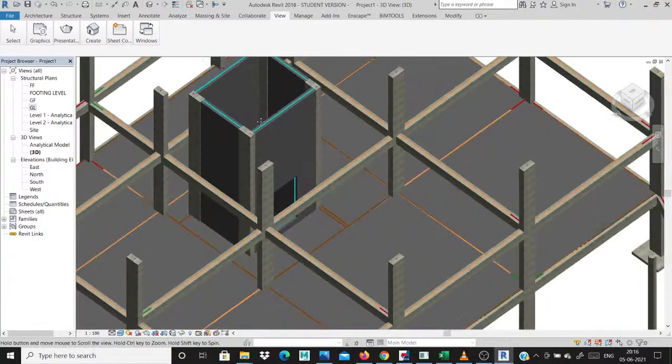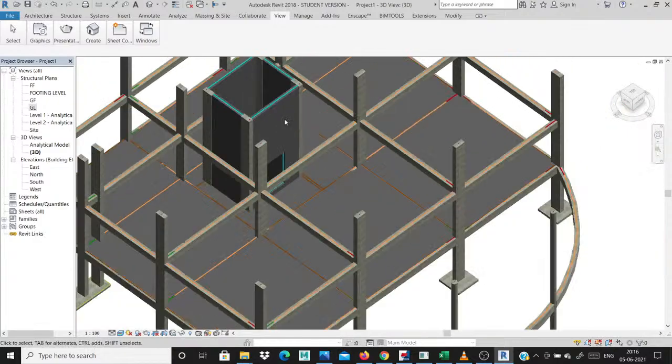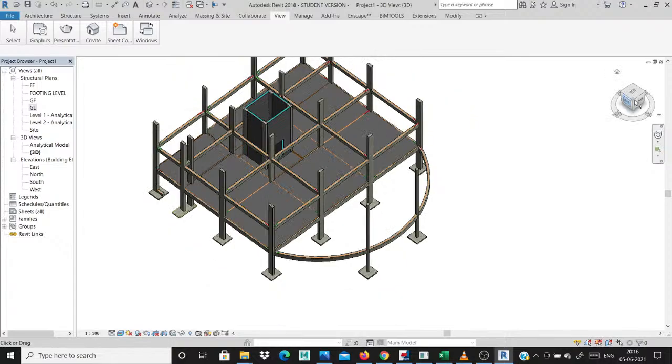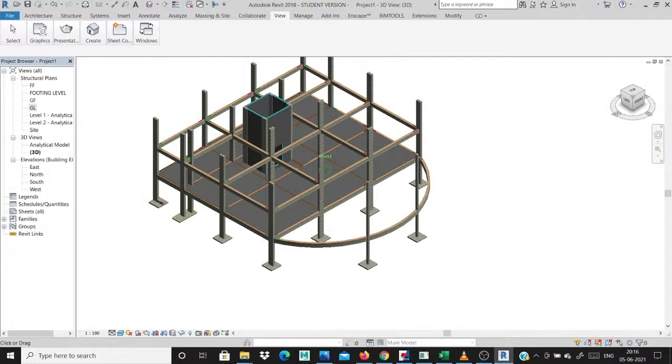You provide the beams also in all the joints, same procedures. Okay, so same procedures. Now I finish this same procedure. I create this floor, and I create the rectangular floor for all the areas, and a line floor for all the areas. Okay, then how to create the next ground floor slab, and how to create this type of arch slab? Simply click this,